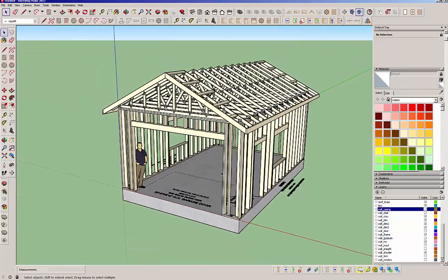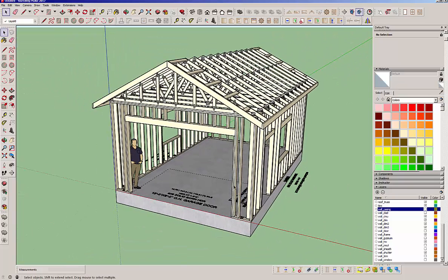Let's go ahead and change this door now, this garage door. As we can see, we've got small shear panels on both sides, where the aspect ratio is probably not right for a standard shear wall. And so in that case, you're probably going to have to go to a portal frame, which is a prescriptive method of handling these sorts of situations. So I'm just going to go ahead and hit the edit opening button.